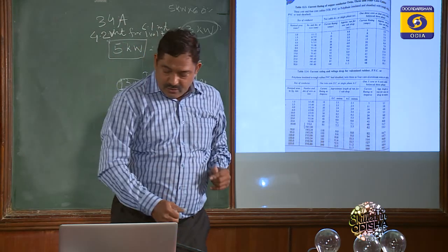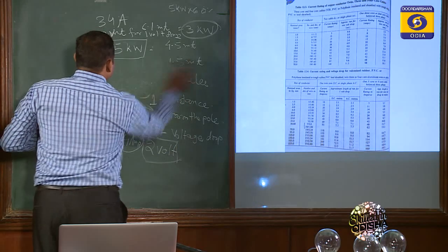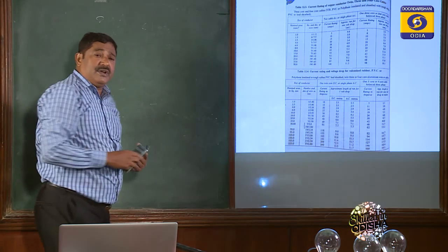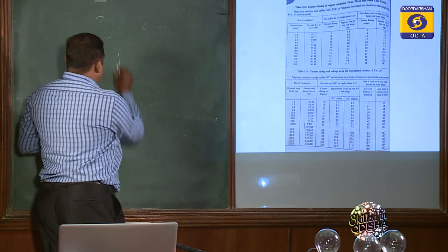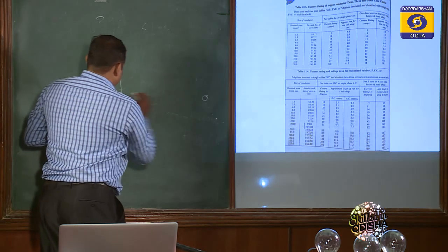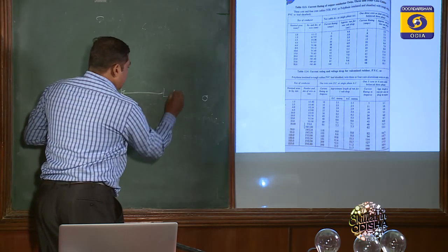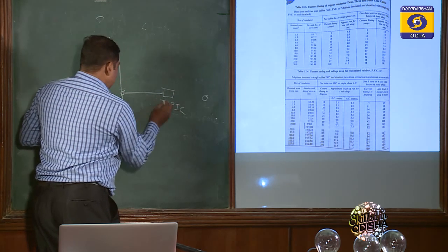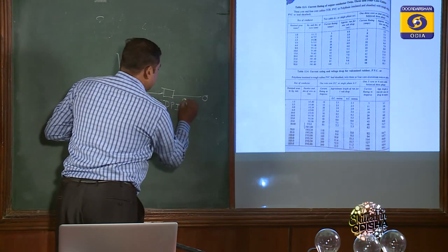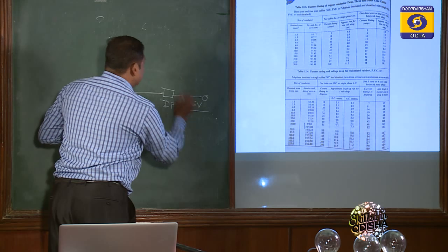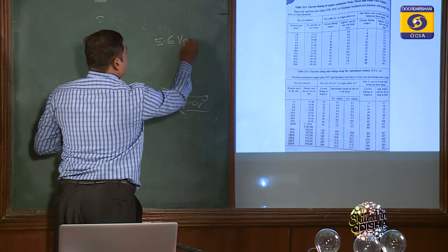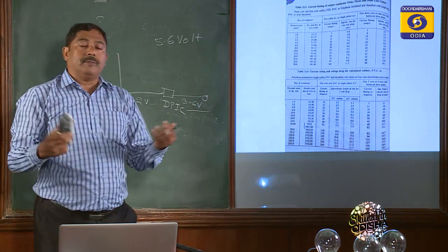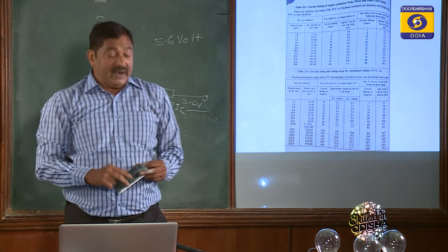As per Indian electricity rules, the total voltage drop from the pole up to the service point, to the bulb, should be limited. Up to the junction box, the DPIC, you can allow a maximum of 2 volts, and here another 3.6 volts. This total of 5.6 volts is the drop we can go for, not beyond that. In that case the bulb will not get sufficient voltage to glow. So that is the main problem.